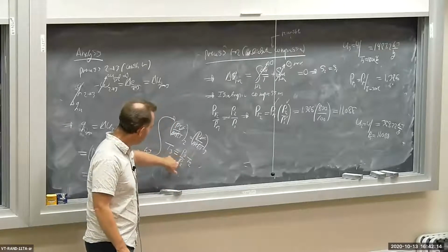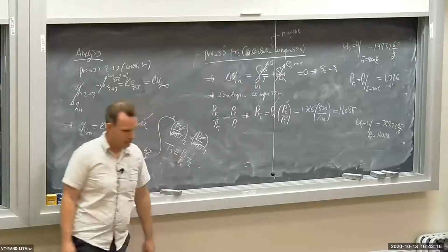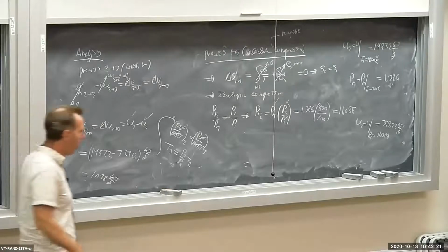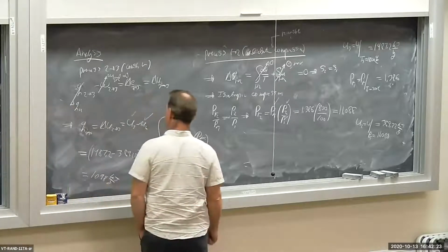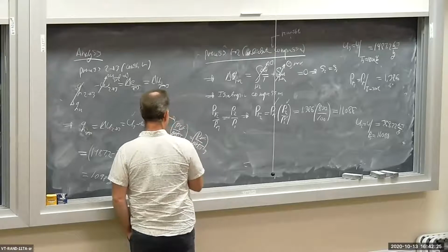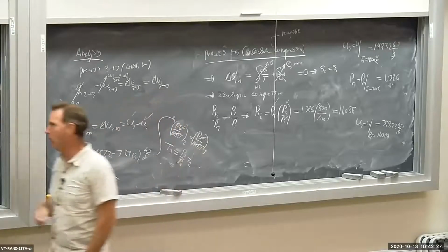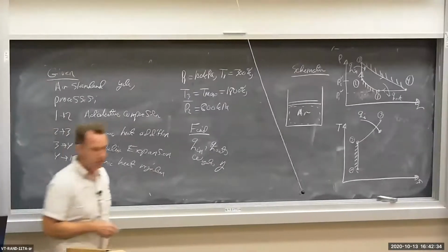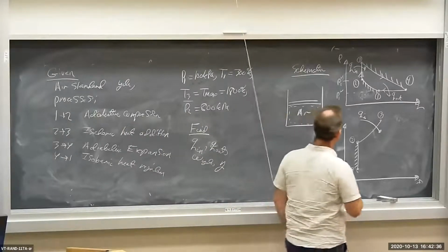Pressure P3 is greater than P2. Pressure's going up as I add heat. It's getting hotter, so pressure has to go up. Pressure goes up, temperature T3 has to go up. Okay, so that's why I know that temperature increases from state 2 to state 3.